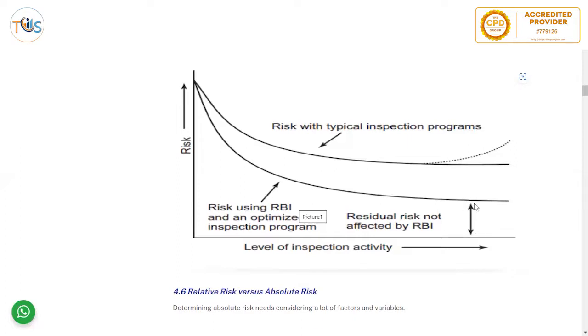There is an amount that always remains, residual risk. And actually, if you use a typical inspection program and increase the inspection, after some point the risk of failure increases because you're opening valves, caps, plugs, and then putting it back together.